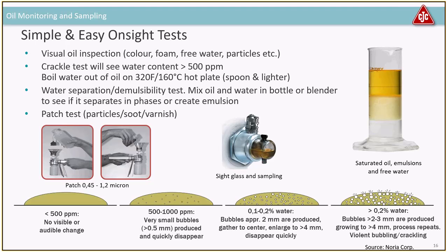There's a few others, of course. You can cool the oil down in your fridge at night, and if it starts to look very, could I say, like cotton candy inside, there's actually varnish in it. There's also the blotter spot test for engines, where you drop a drop of oil onto a kind of paper, and so there's many different tests.